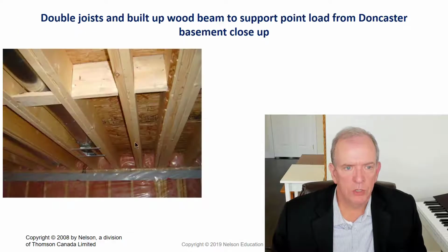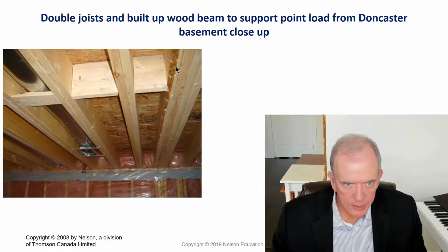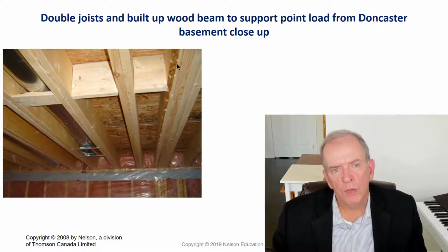So here's an image. This is a built-up wood beam, and there's 1, 2, 3, 4 plies. And you see this little strip here? Remember when we talked about the grading of lumber? Well, that one made it through. Always with lumber, some of them make it through, but not too many. This would be a number 2 grade, but it has wane.